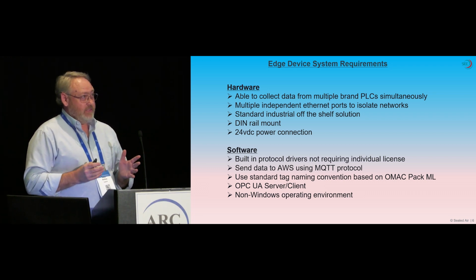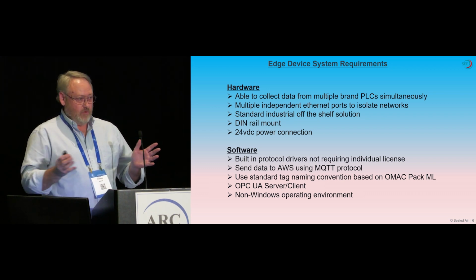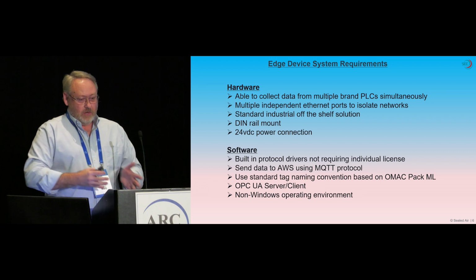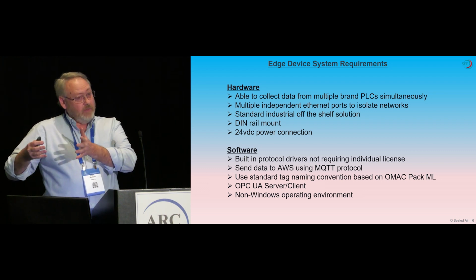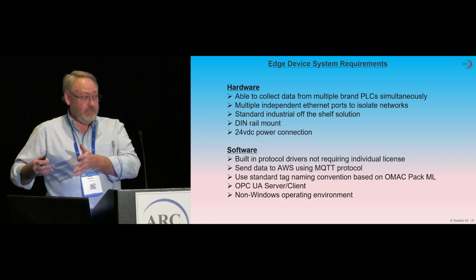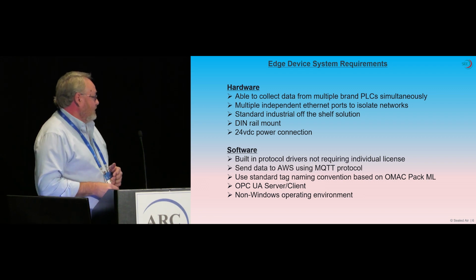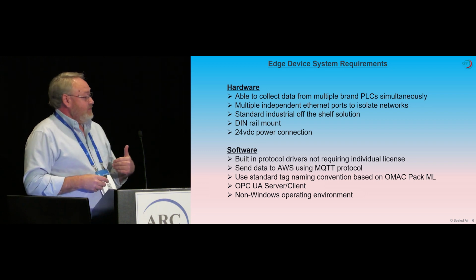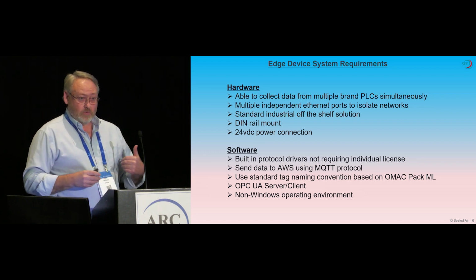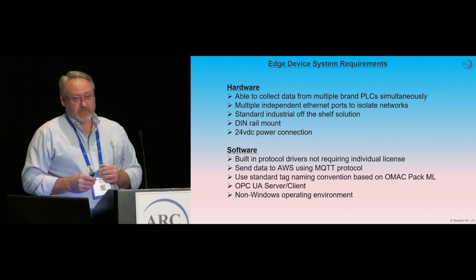And what that provides us is, as the data from all these different platforms and all these different controllers is pushed into the cloud, we're able to create dashboards with standard templates, with standard naming conventions, regardless of the machine itself. Okay? We wanted to use OPC-UA as another option for communication protocols. And we wanted a non-Windows operating environment.